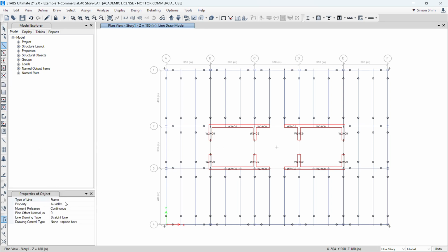So click the beam. I'm gonna choose link beam. But see that wall thickness 24. I'm gonna click the 24 by 24. I'm gonna add this wall. But make sure this is concrete construction. They are a monolithic pour, so this should be a continuous member, no moment release, right? So I'm gonna draw this.